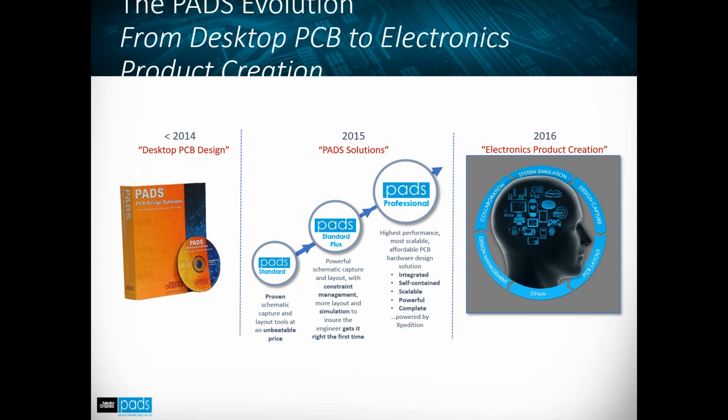PADS Standard and Standard Plus are all based off of PADS layout that has been around for a long time. PADS Professional is a very new tool, at least in the PADS space, and it's very similar to Expedition layout. Again, this can offer some great benefits if you're doing some very complex designs with fine pitch BGAs or very high-speed buses, anything like that. PADS Professional can help you with that.